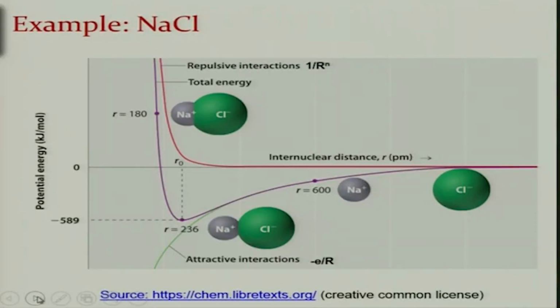But if you look at magnesium oxide, nickel oxide, iron oxide, they are higher melting point. If you look at Y2O3, ZrO2, TiO2, even higher, Al2O3 higher. So, because of higher Q and as a result more negative energy. So, this is the fundamental basis of the ionic solid, and this is how you plot, for example, for a given material.